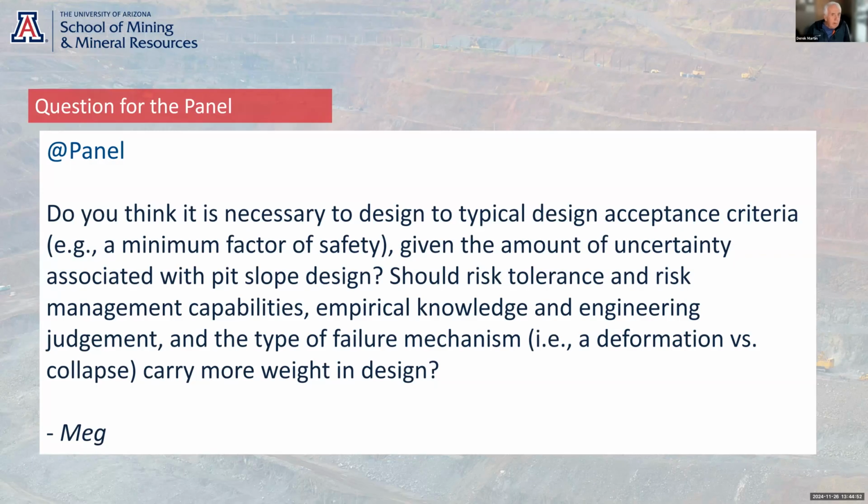Recognizing that you all have to start from somewhere. At a green site, the factor of safety has to be done in the typical precautionary approach that we use in engineering. But once you move to operations, we measure deformations continuously. We measure pore pressures in some mines, not all of them. So the performance can be measured using the tools that we have to measure how the pit walls behave.